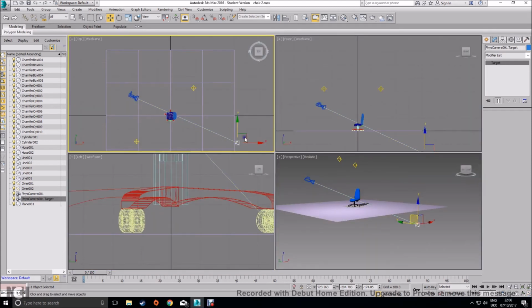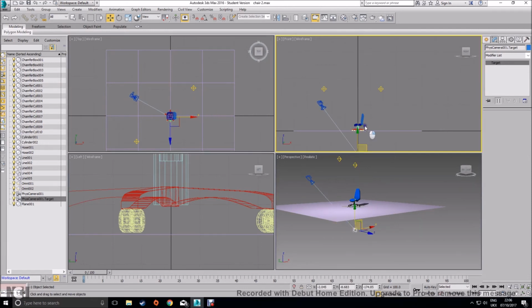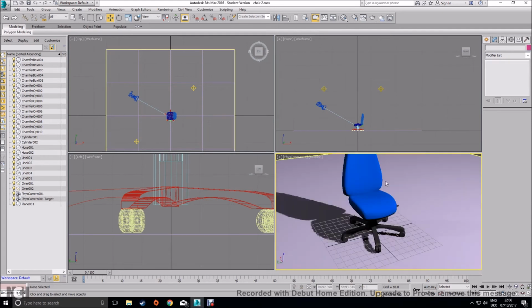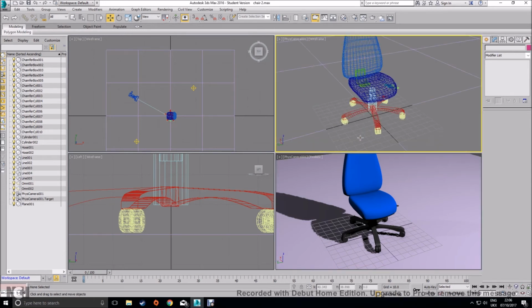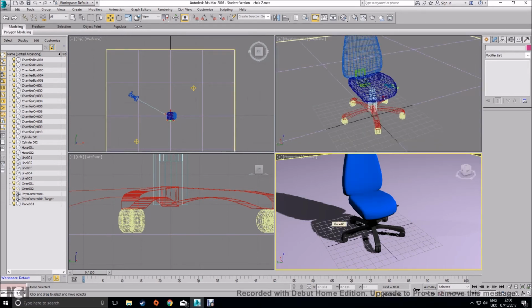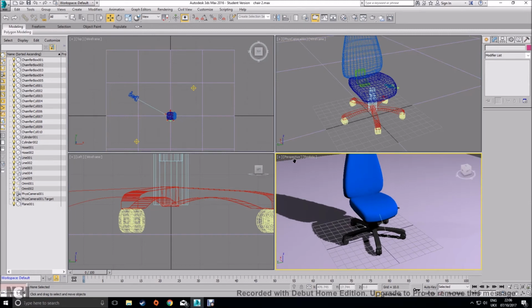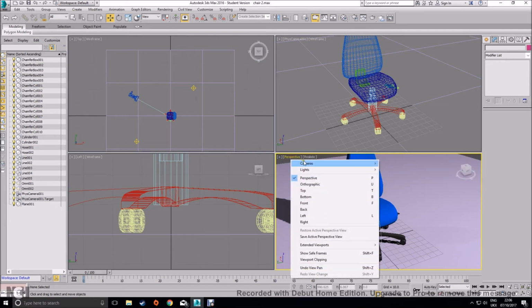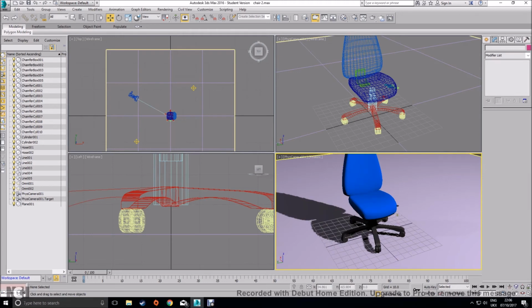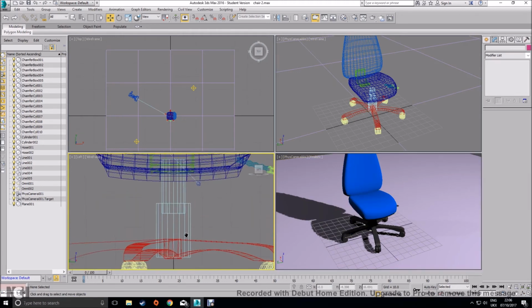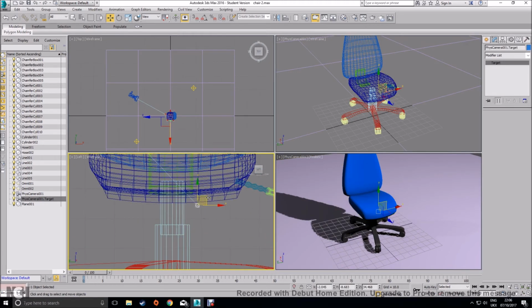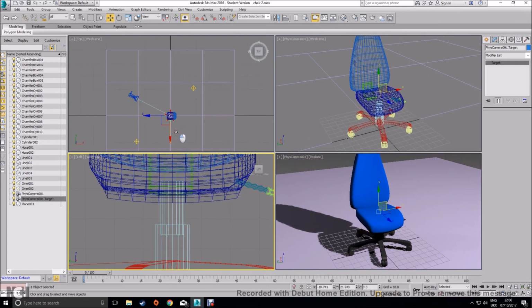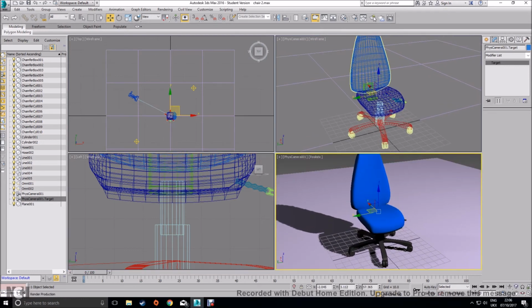I'm just going to position the target so it's smack bang on my chair. And then I'm going to press C to jump back to my camera view. Notice I didn't need Control and C, just C. P for perspective, C for camera. Or you can just click on perspective or the view and change it to whatever you like. You can have multiple cameras in your scene, by the way. You don't just have to have one, and you can jump between them. I'm just going to line that up so I'm happy with it. I think about that looks good.